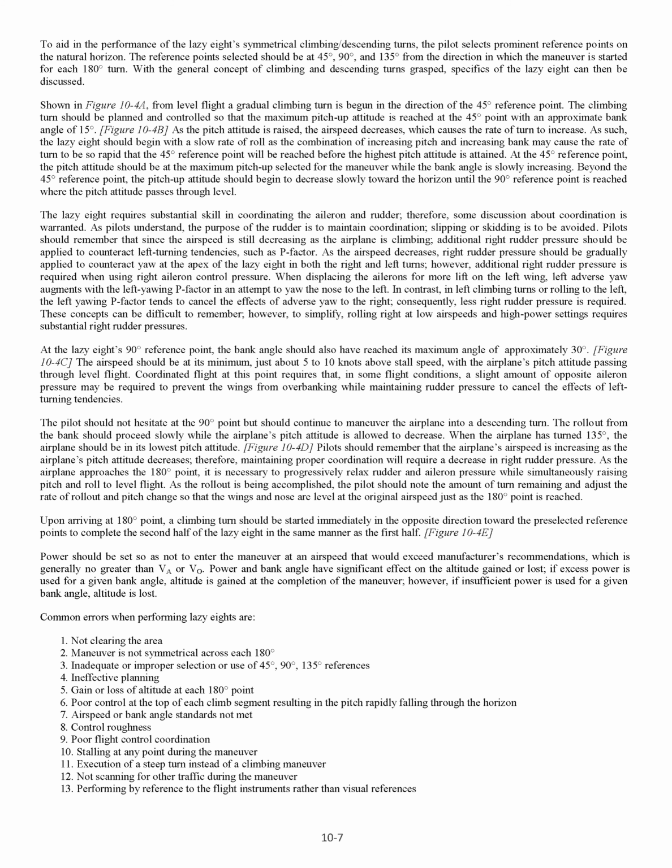Pilots should remember that since the airspeed is still decreasing as the airplane is climbing, additional right rudder pressure should be applied to counteract left turning tendencies, such as P-factor. As the airspeed decreases, right rudder pressure should be gradually applied to counteract yaw at the apex of the Lazy 8 in both the right and left turns.